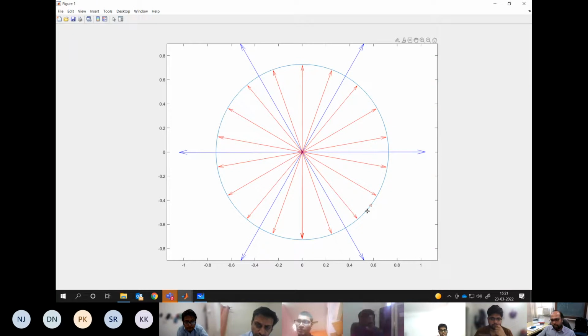What we are doing, as it is moving, during one sample period, we are applying the vectors. Say, for example, from this point to this interval, we have applied 0, 1, 2, 7. And the resultant would be this vector which is lying in this sample. The voltage vector is rotating continuously in response to our theta, which we have generated.